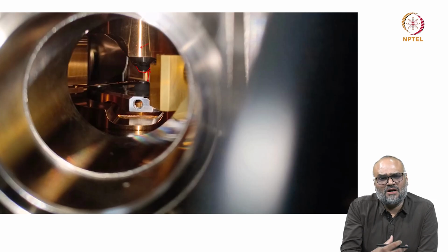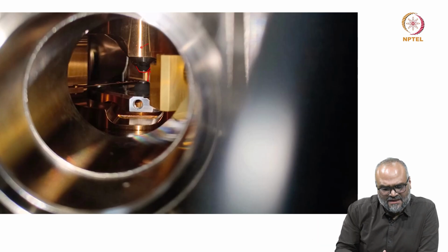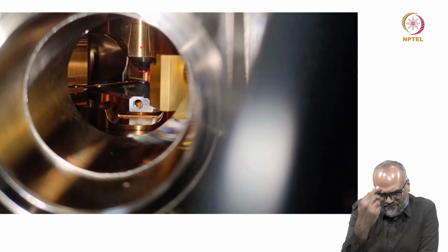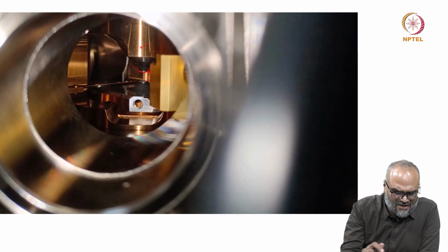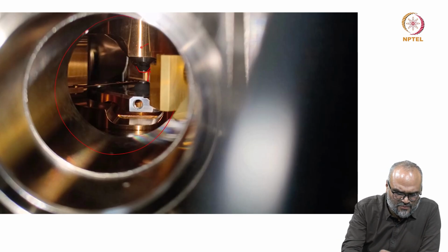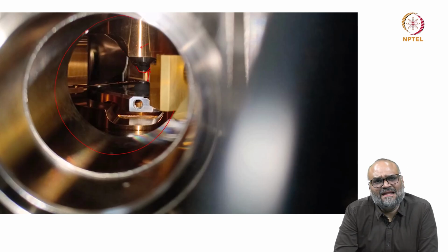You cannot get water into the microscope column, so just by conduction you want to extract the heat out, with the convective flow of chilled water. This is all inside the microscope column, and it is all at ultra high vacuum. But we opened up one of these ports here to just get an image of how the lens is.